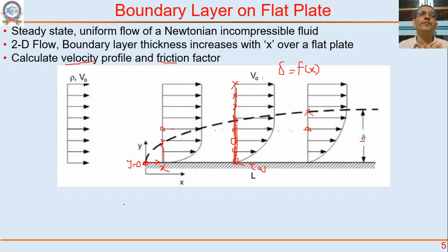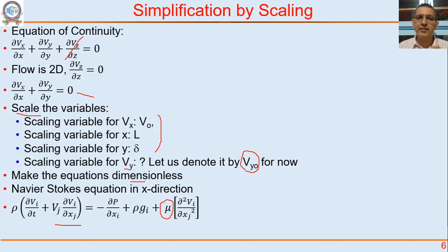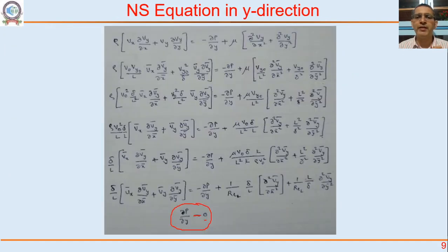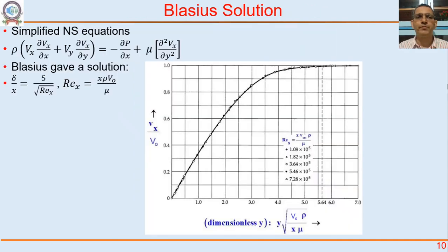Euler number, Reynolds number is large. We can neglect the viscous terms. We can just use the convective and pressure terms and get a pressure field. The simplified version of the Navier-Stokes equation will give us the pressure field, and that pressure field will be the same as inside the boundary layer. Make sure that you understand each sentence before going forward, because all these are very important terms.